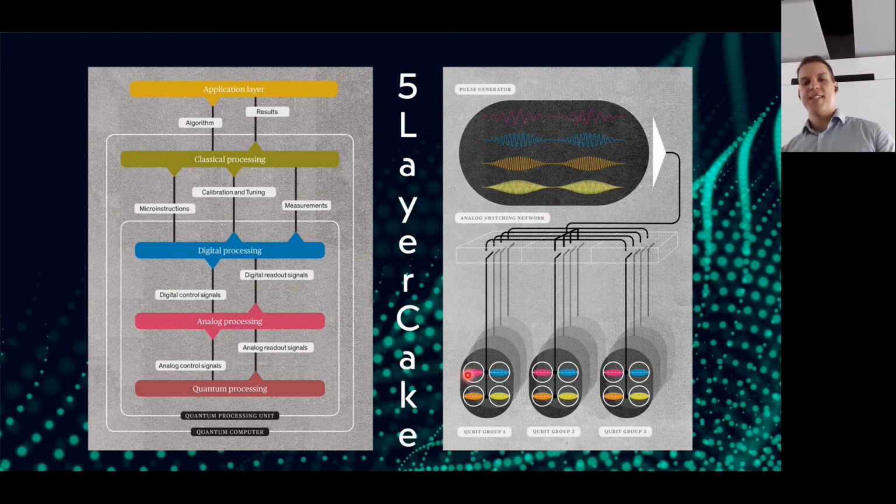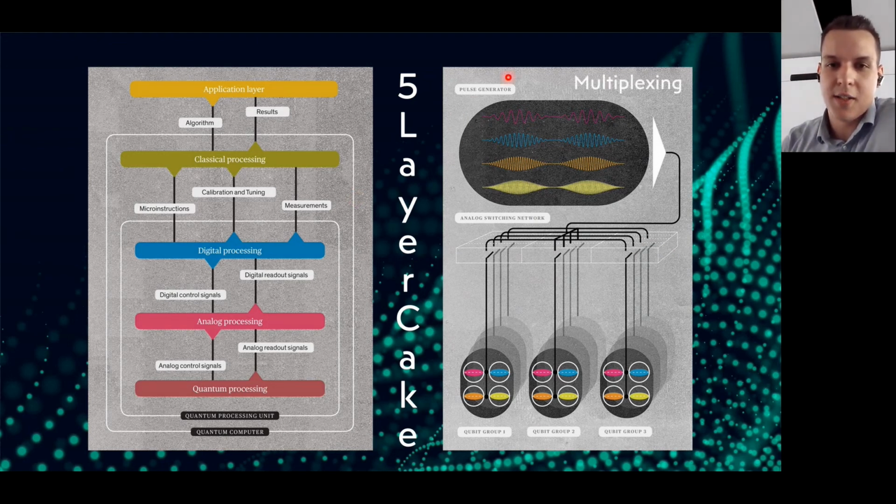And then you say, I send 6 gigahertz to group 1 with 100 qubits. And in the group itself, you have different signals, frequencies. So then you have a less high bandwidth because you send to groups and not to singular qubits. And this is also a part of error correcting, so that we can have that many qubits. The whole thing here is called multiplexing. I just want to take it up as an example because you always see complicated words, but if you translate this, you see, okay, it's bundling together. Okay, we summarize something. Summarizing of signals is key to make a large-scale quantum computer.